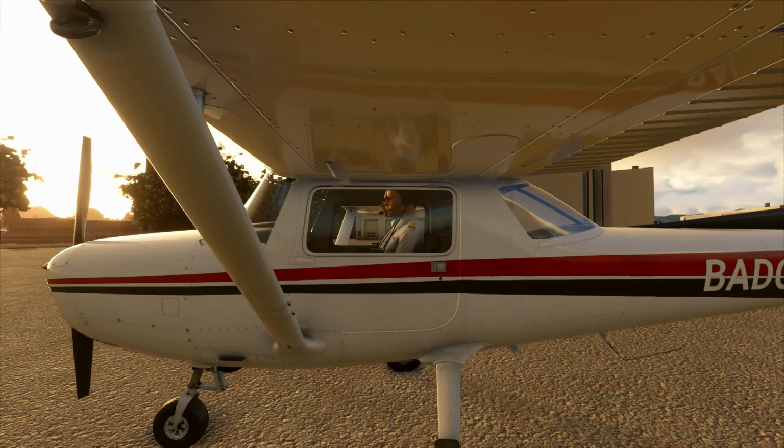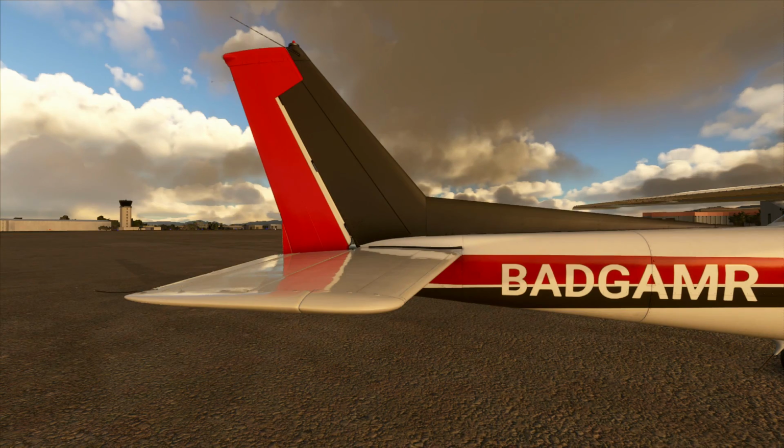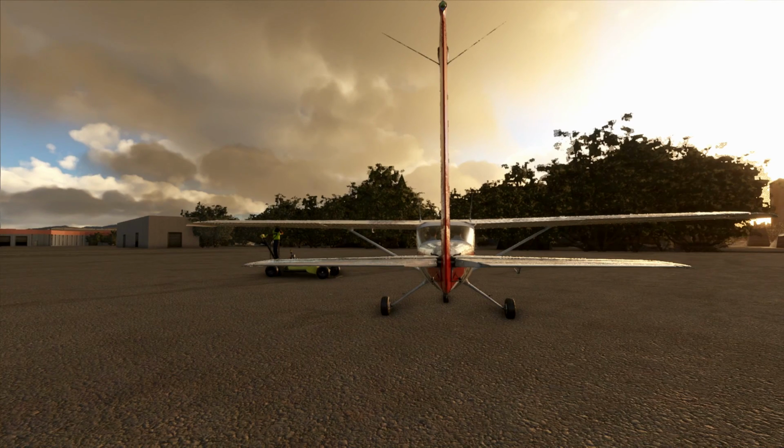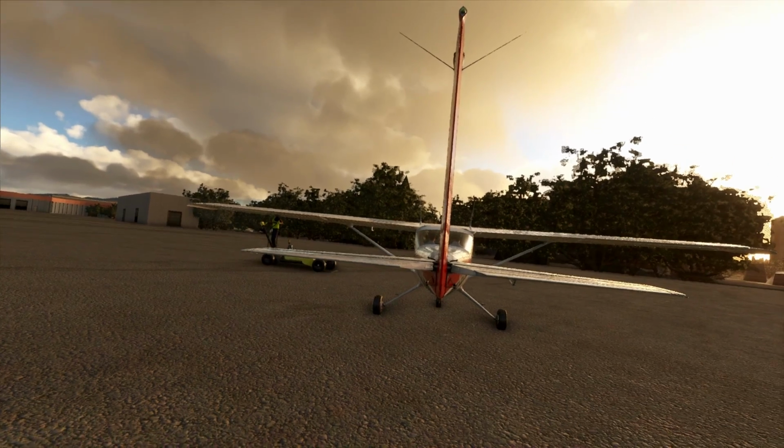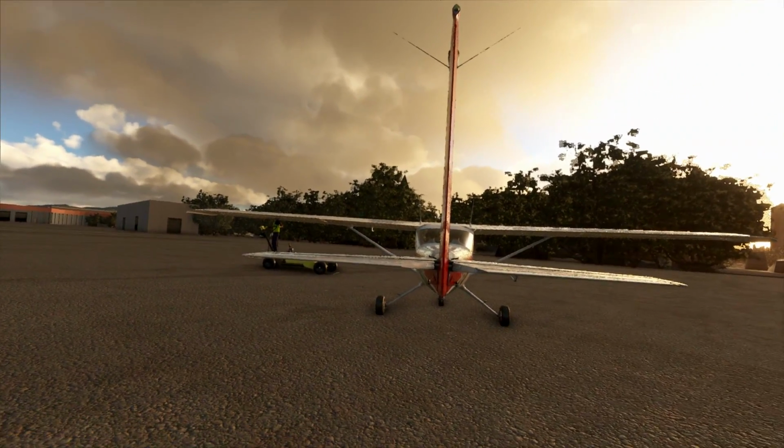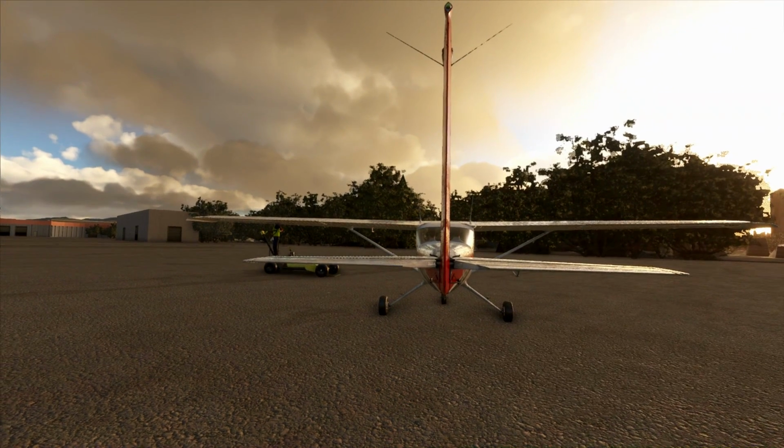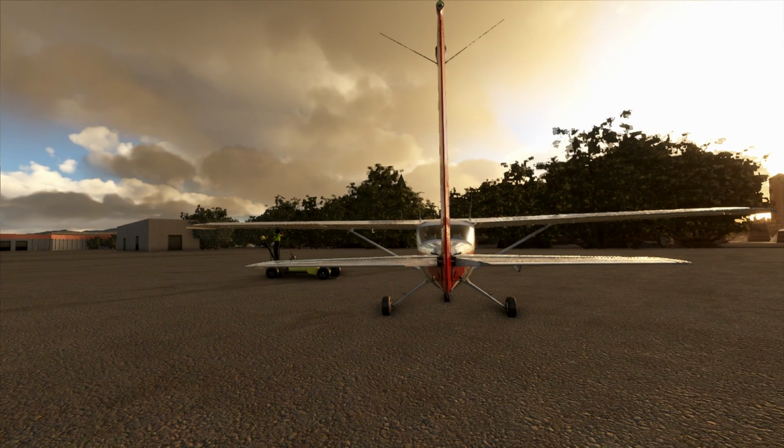Section 2 focuses on the fuselage and empennage of the airframe. We need to ensure that we have the correct fuel type and we don't have condensation in the tanks. Some aircraft, such as the Cessna 182, have a rubber bladder in them and can trap water in the folds. For these situations, the PIC should rock the aircraft back and forth in an effort to move that water into the main tank area where it can be detected and removed. Obviously, we're not doing that here.